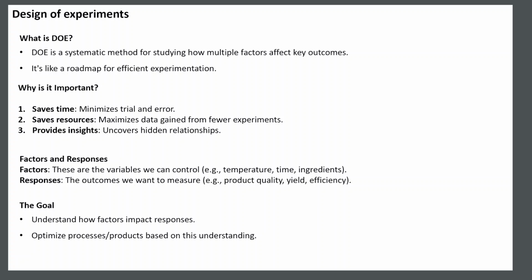Before moving further, we should understand the terminologies which we generally use in the design of experiments. If you just open any design of experiment, the two terminologies which flash are factors and responses. Factors are nothing but the variables which can control the outcome. For example, in any testing, temperature can affect the mechanical properties.